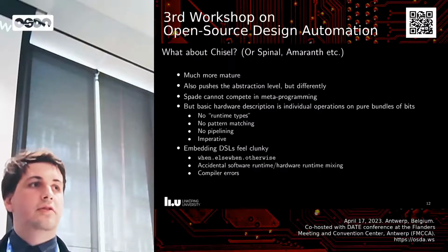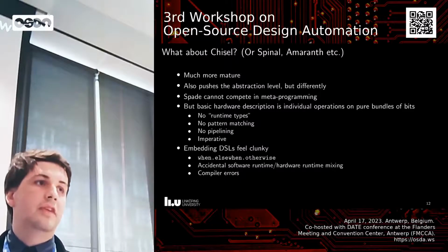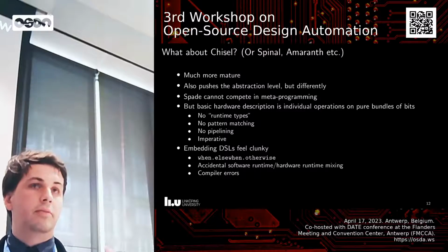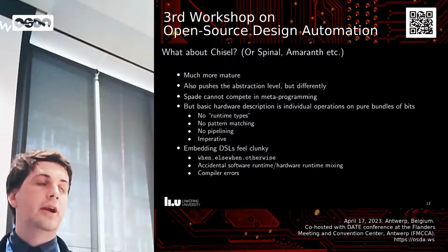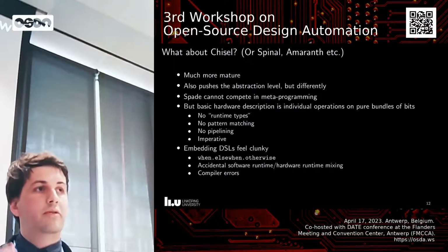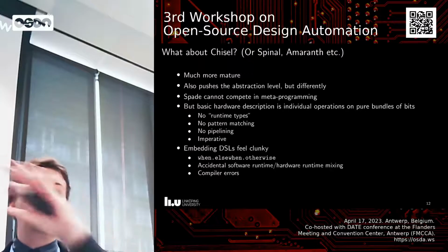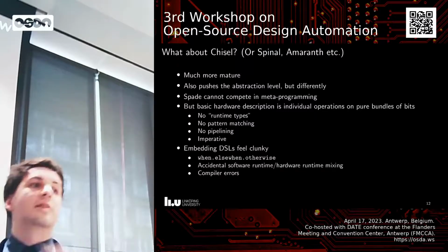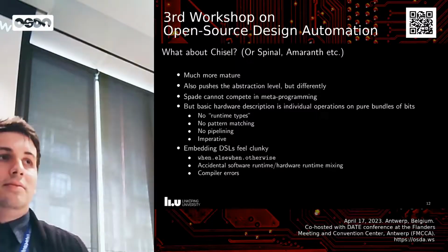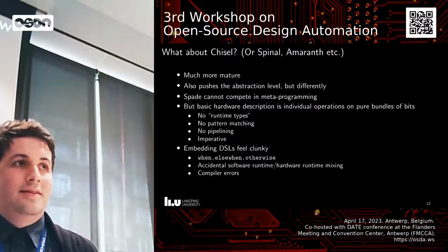It's nice to have things to borrow from with your typing. A thing that isn't a thing in software, but is a thing in hardware, is modeling ports. I didn't get into that here, but I have a system similar to the lifetimes in Rust, for modeling so that you can only use a memory port, for example, once. If you try to give a memory port to two different independent circuits, the compiler would say, no, it's being used twice. Okay. Yeah, that seems to me going a bit heavily on the Rust side.